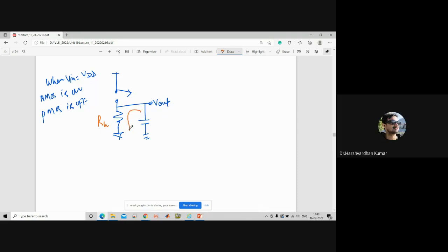So in this case, the accumulated charge across the capacitor will discharge. We can say that the output node is connected to the ground. Correct? Now, second case we will discuss here. Then we will write a point about it. Why is the output node connected to the ground node? Because at the ground node, the impedance is low, and we also know very well the output impedance of CMOS is also low. Okay, now we will discuss the second case.